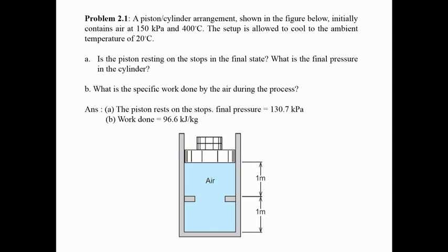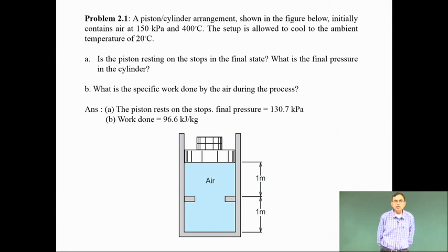So, you have a piston cylinder arrangement. It initially contains air at 150 kilopascal and 400 degree centigrade. The setup is allowed to cool to ambient temperature of 20 degree centigrade. The question is, is the piston resting on the stops in the final state?